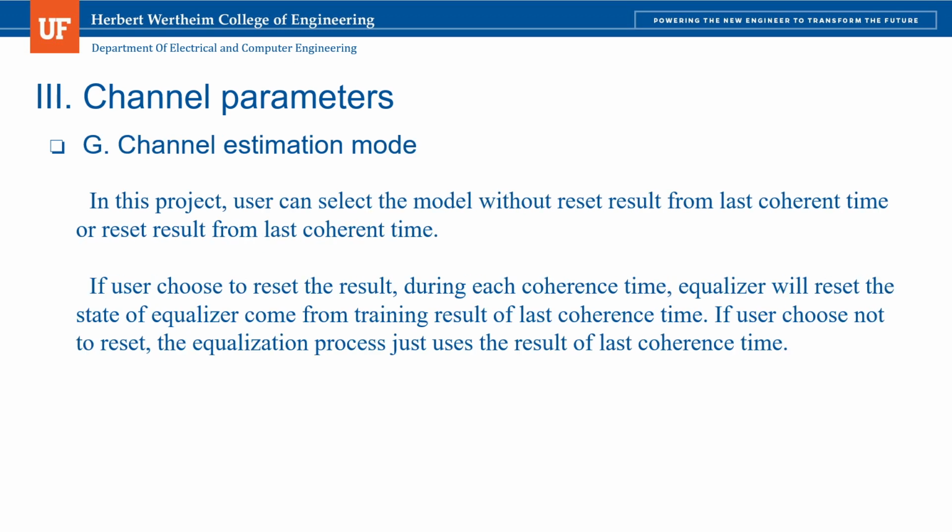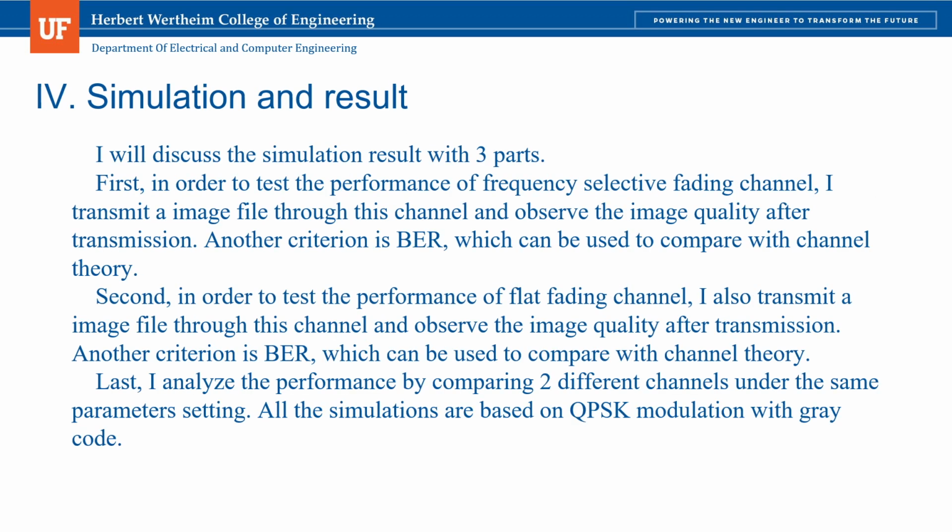And this part is about the channel estimation mode. In this project, the user can select the mode without resetting the result from the last coherence time or with resetting the result from the last coherence time. If the user chooses to reset the result during each coherence time, the equalizer will reset the state of the equalizer from the training result of the last coherence time. If the user chooses not to reset, the equalization process just uses the result of the last coherence time.